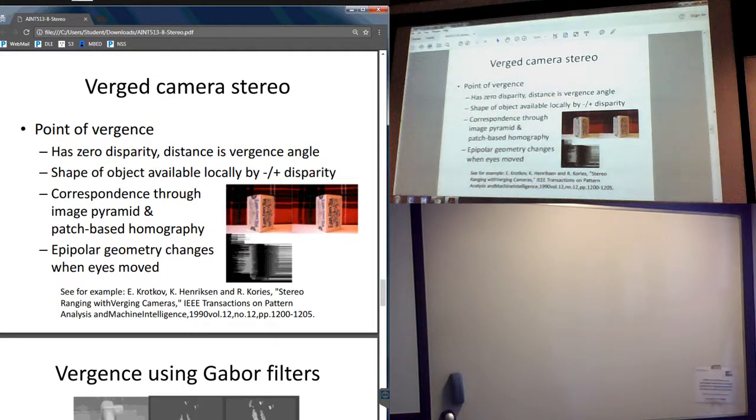Do you mean to say they actually use the data from the infrared sensor? Yes. They merge them because they know the field of view of the optical camera, and the infrared sensor in the Kinect is off to one side, and the light is strobed across the field of view, and the echo that comes back is a modulated beam.